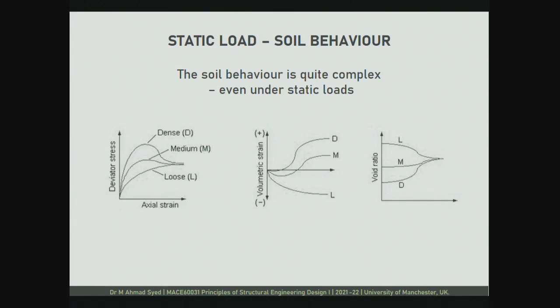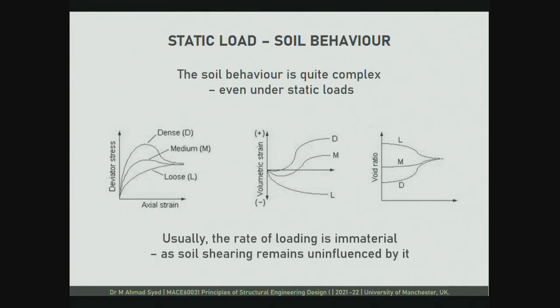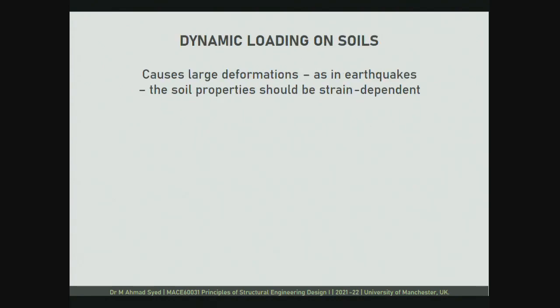Now usually the rate of loading is immaterial for static tests, because for the type of structures that we normally deal with, how fast and by how much we apply the load on a given soil mass is not very significant, as the shearing behavior of soil usually remains uninfluenced by it. But on the other hand, when we have dynamic loading as induced by an earthquake, we are looking at large strain behavior, because an earthquake is going to cause large strains.